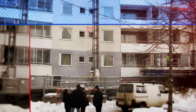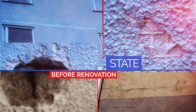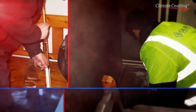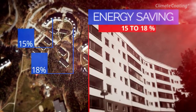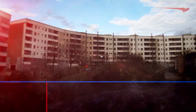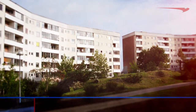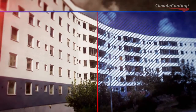Back in 2009, a project in the Swedish town of Botkyrka was guided by an independent institute. A thermoceramic membrane was applied as a wall paint to an existing facade. The measurements, produced by one of the largest energy advisors in Sweden, showed an energy saving of 15% and more in comparison to non-renovated facades. Here, big buildings are at stake, so we may conclude that the results are representative as a result of low variance. We are talking about just a 0.3 millimeter ceramic coating applied to the facade.